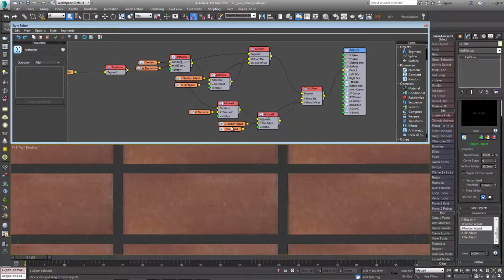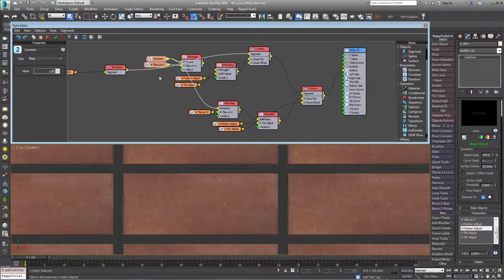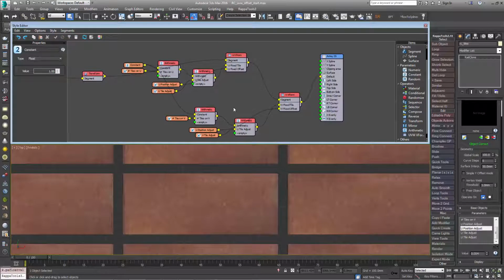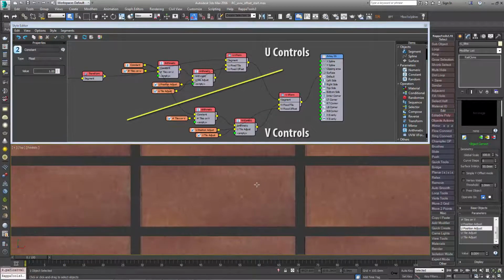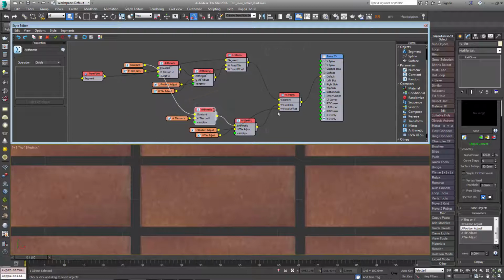This enables you to set a range for the tiling, offset and rotation of the UVWs, and optionally use a step value as a multiplier to return values from within that range. Fortunately, we've already calculated the correct step values by dividing 1 by the number of tiles, so we just need to export some values and hook up the existing arithmetic nodes.